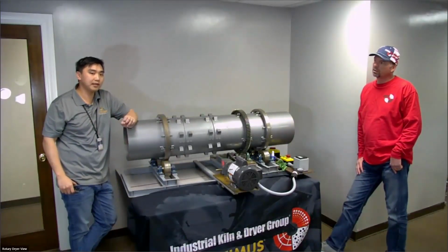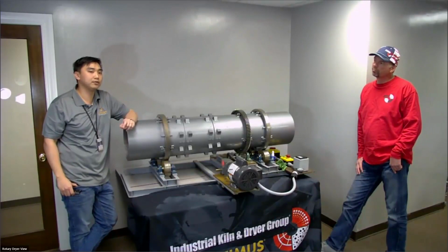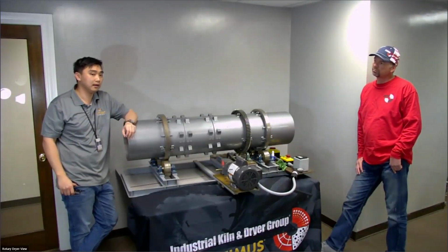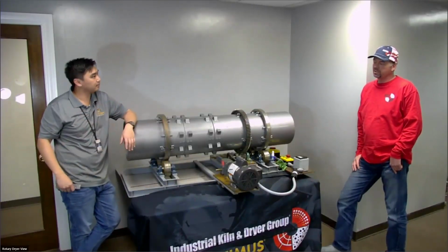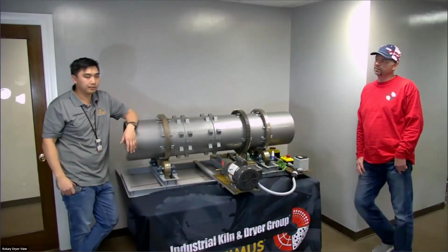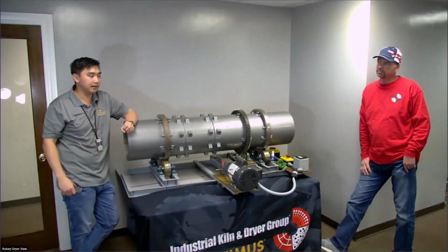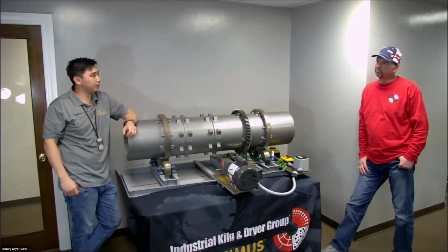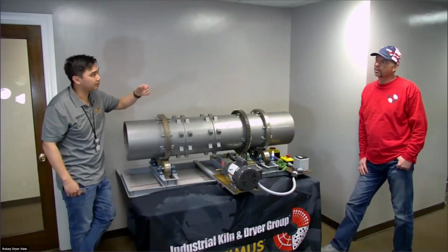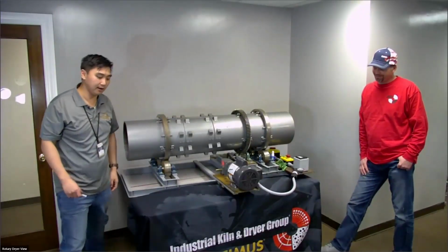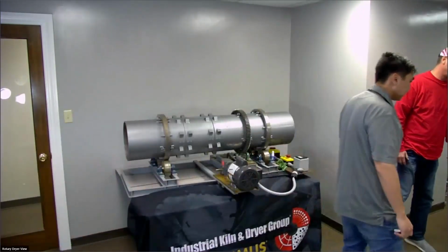So one of the things I always look for is if there's a shiny spot, you've already screwed up. You need to go ahead and put something there, a little piece of angle, maybe throughout. A lot of times just some three-quarter, quarter, whatever it is, just to break it up. Because if you keep doing that, eventually the shell will thin out and we'll have two pieces. Okay, so let's go back to the presentation.